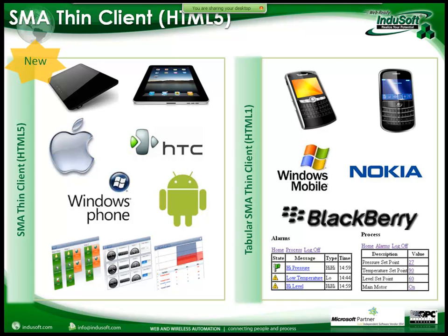And InduSoft has built-in tools for remote notification as well. So when alarms happen, InduSoft can send alarm messages by email or text messages, and then you can connect to the system using your mobile device or a regular PC and monitor or troubleshoot the situation, make decisions based on online data and history data collected by the system.